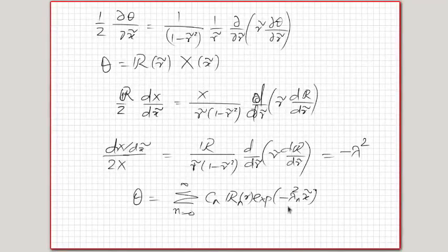And it's a series solution which is convergent because lambda n would go on increasing as n increases, and the terms will be convergent. So this, along with the boundary conditions that theta is equal to 1 at x is equal to 0, because theta is T minus T wall divided by Ti minus T wall.